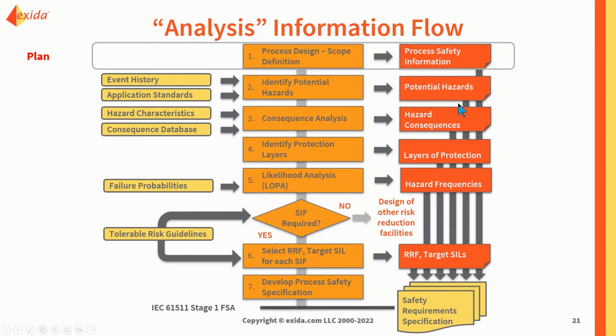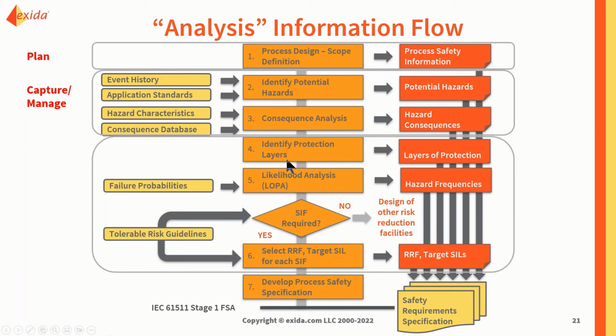And after you have the plan, we try to do the PHA, which is a kind of analysis and also a kind of capture, and also trying to manage a little bit of the data as well to derive some of the hazards and the consequences, so that we can pass them into the lower part, which is basically an analysis of the IPLs, the layers of protection, to see whether those safeguards are actually useful or not, whether they can actually be qualified as safeguards or not.